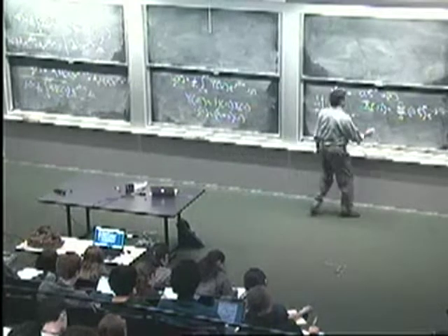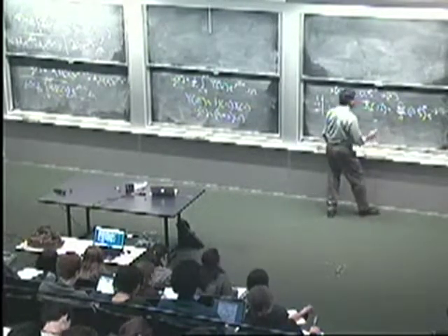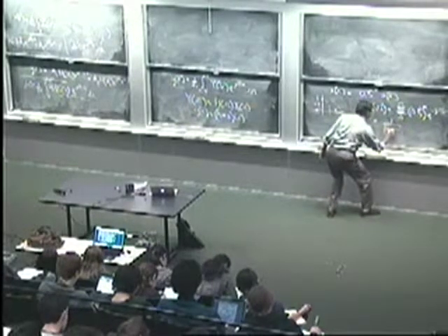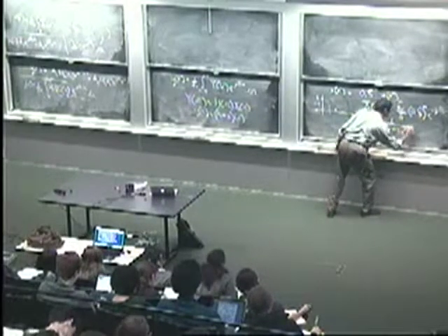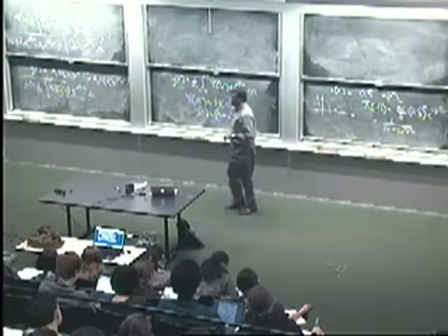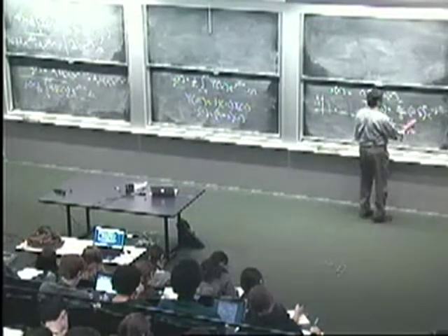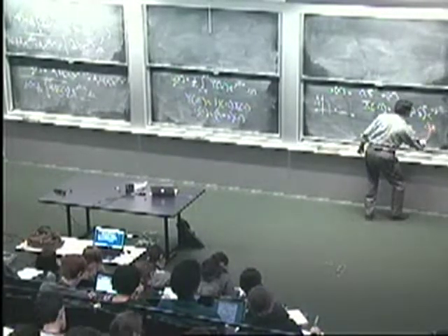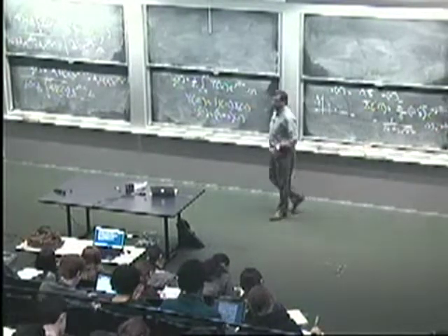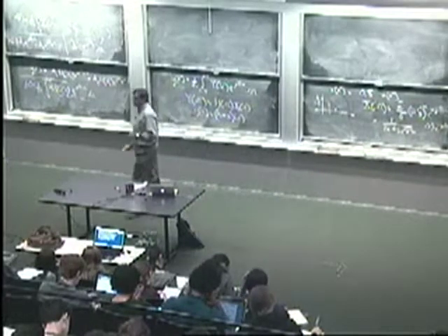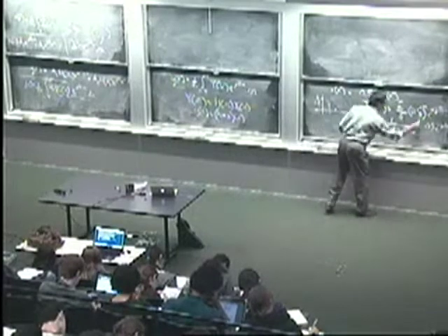Okay, so you can now sum an infinite series here, and what do you get? You get 1 over 1 minus 0.5 e to the minus j omega. Right? It's just summing a geometric series. Because each term here follows from the previous one by multiplying by the factor 0.5 e to the minus j omega. Right? So it's a geometric series with that ratio, and so this is what the sum works out to be.